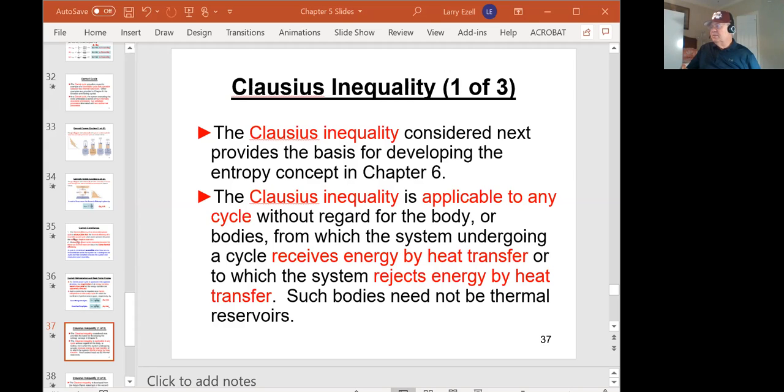Now that on its own violates the second law of thermodynamics, but we have to put work in. When you put work in, well, that's what the second law says: you can't transfer heat from cold to hot, that's going uphill, without putting some work in. So there's the refrigeration cycle, an air conditioning cycle.